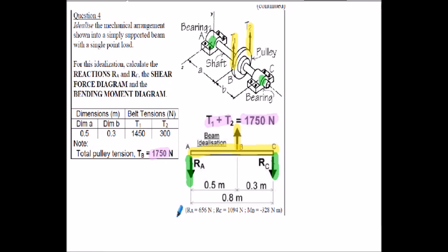So basically we've got a simply supported beam with a load in the middle. The directions of the loads, or direction of the arrows here, are slightly unusual. We normally find the arrow above the beam going down and the reactions going up, but in this particular case with the scenario, the central load in the beam is going up, so the reactions must go down. So as usual, the first thing we're going to do is calculate the reactions of the beam. So we're going to take moments about a point, and I suggest as always we take moments about point A to find the reactions.